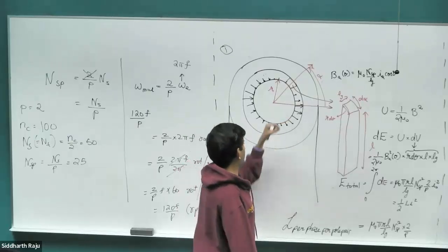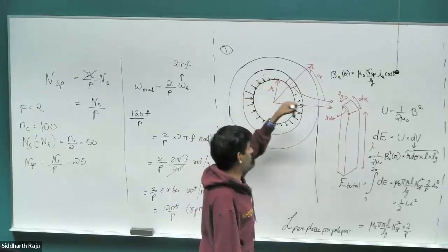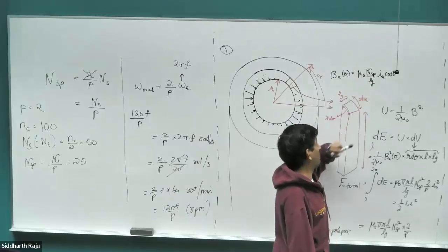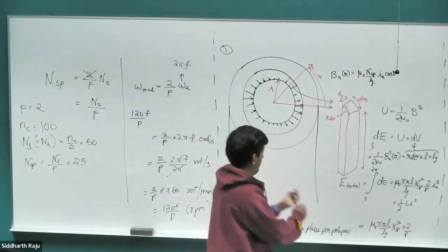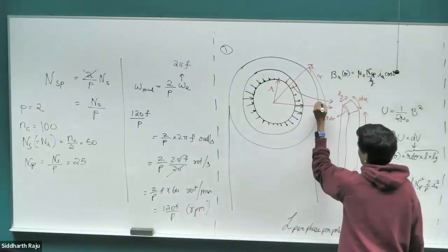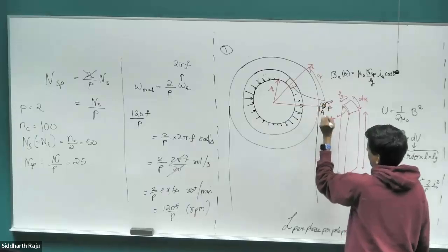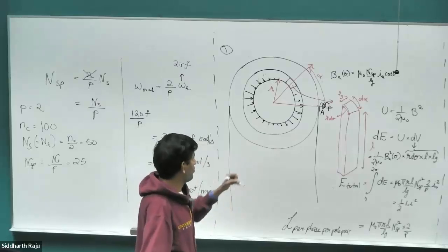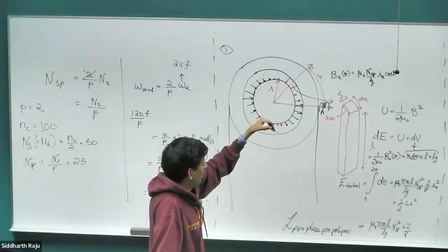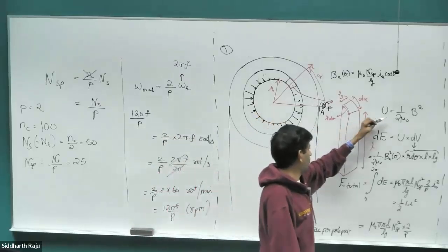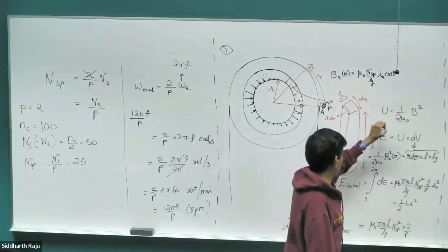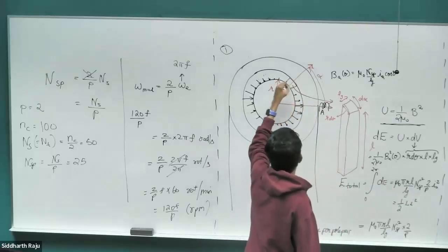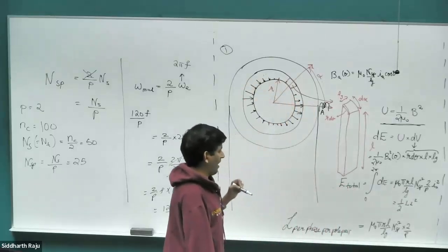All right. So since our B field is varying in the air gap, which we have already seen what the formula is, right? Mu naught N_s over P divided by g times i_A cos of theta, just for one phase. So right now we are only considering a single coil, just the A phase coil alone. We are not worried about what the B and the C phase coils are up to. So for that we have the B field there, and the energy density is just B square divided by 2 mu naught, which you have derived in the past. So you substitute the B value, you have the energy density at every single tiny point in the air gap.